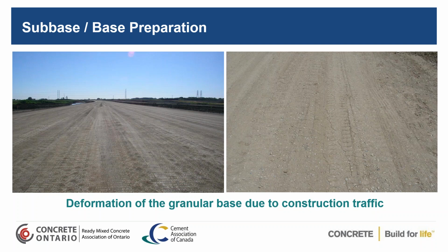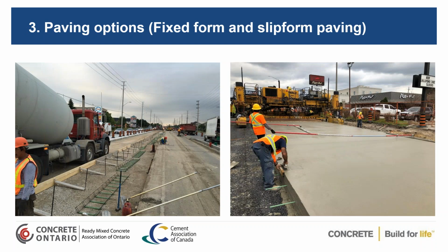So you're going to have an overrun on your concrete. But not only that, if those ruts are deep enough, you can actually prevent your concrete from shrinking as it's losing its moisture. And then what you're going to do is possibly cause some longitudinal cracking. So you want to make sure that you have a good performing granular base that you're placing on, and that you don't have issues with soft spots, which are going to be removed, and you don't have rutting built into your aggregate base.